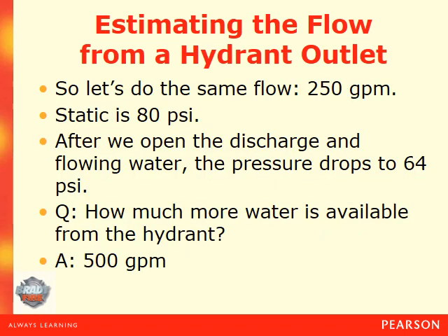So let's do the same flow. 250 gallons per minute and the static is 80 psi. After we open the discharge and begin flowing water, the pressure drops to 64. How much more water is available from the hydrant?